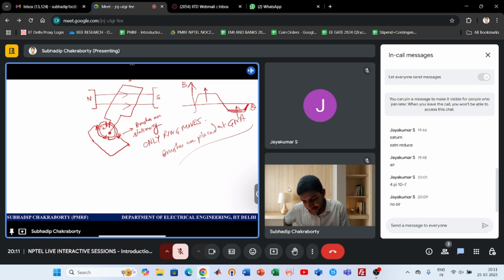But as you understand, once you approach the pole, the DC machine is like flat top, right? Once you approach the arc, the flux density is almost constant. Then it reduces again as you move away. And as you go again to the south, it is in the other direction. And it goes up. So like flat top, right?